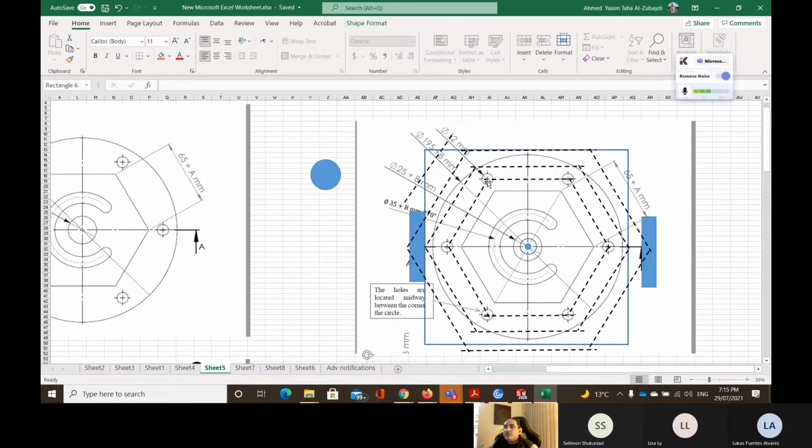Okay, with the schedule lines we found the points, and then we simply connect them using G code: G00 to above that point at a height of, let's say, 5 millimeters in Z. Then G01 to Z equal to -4. Then you follow the lines all in G01, come back to the same point, then G01 to the inside offset, and repeat the same process.